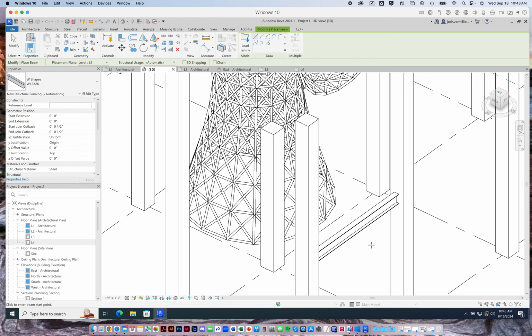Right? Okay. So what I'm going to do is I'm going to think about that beam, and right now our beams are like as if we were stepping on the beam on the second floor. Right? They come right up to that finished floor level. When in fact we have a slab and then corrugated decking underneath that slab, right? And then we have beams underneath that, running up the slab of the deck. So what we need to do is we need to offset this down, anticipating how much floor we're going to have on top of it, right?